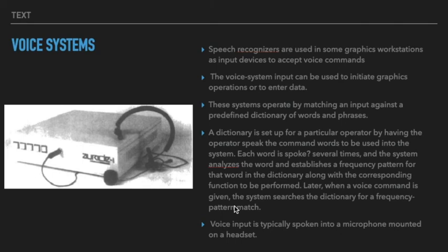A dictionary is set up for a particular operator by having the operator speak the command words to be used into the system, and each word is said several times, and the system analyzes the word and establishes a frequency pattern for that word in the dictionary along with the corresponding function to be performed.